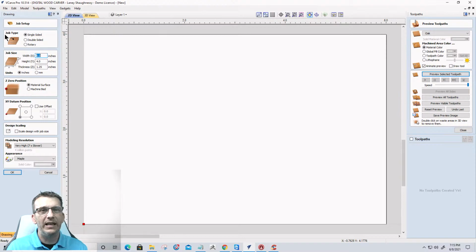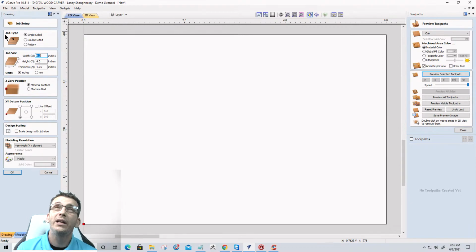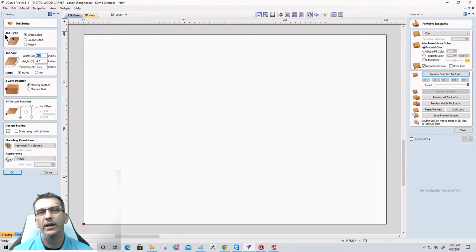And then if we do anything like inlay work or laser engraving on the lids or anything like that, it'll really stand out. So we're going to work on the base first, and I'm going to be drawing the lid in here as well, but we're going to transfer the lid over to another design file, basically, with the appropriate thickness on that. When it comes to the lids, I'm partial to 3/8. We can go 1/2 inch or less, but 3/8 is a really nice lid. If I'm working with 3/4 inch thick material, then maybe we can bring that lid size down a little bit narrower and skinnier. But for this project, we're going to go with a 6" by 4" block.